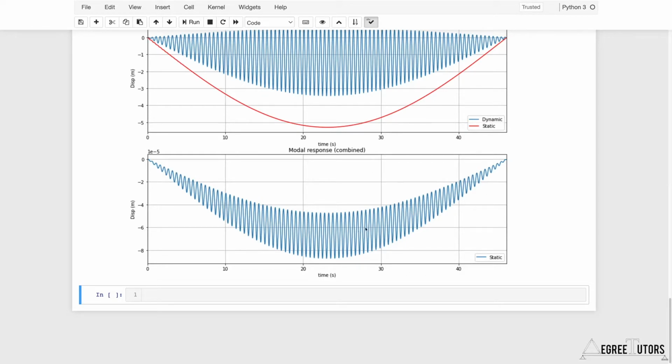But when we start to simulate 100 or 200 people walking across this bridge, the vibration response of the bridge is going to get very messy looking, and it's going to be quite handy for us to be able to just pick out the displacement envelope from that messy oscillation. So I'm going to write a little function that allows us to feed in this displacement and the time vector, and it's going to search through and identify the time and the magnitude of each of these oscillation peaks so that we can plot an envelope over the displacement.